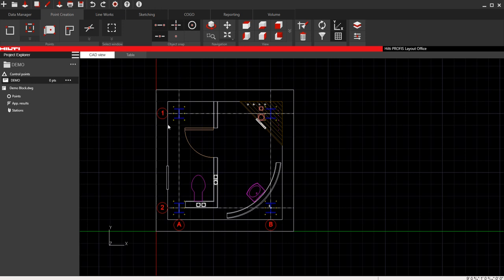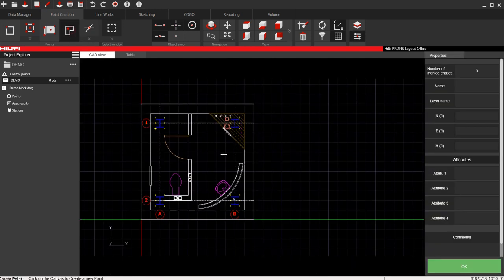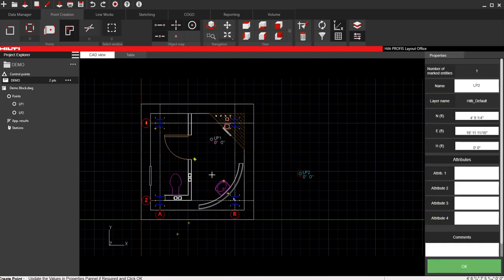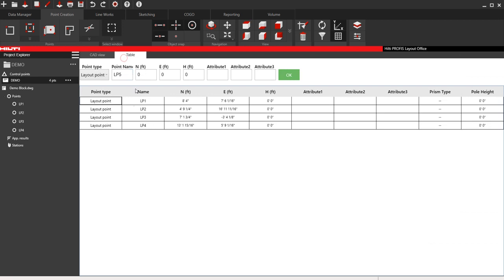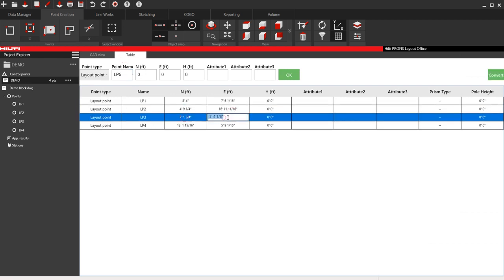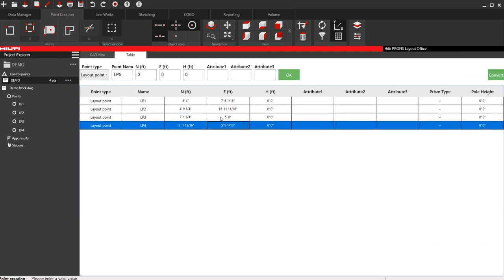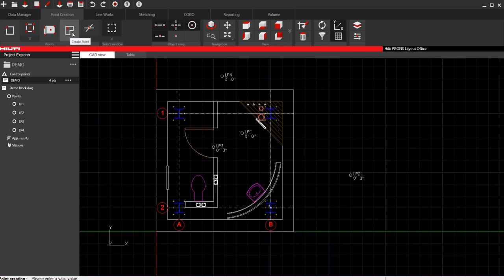So to finish up the point creation here, we're going to go to create point anywhere for a second, and this is literally just putting points out in the field, and you can come over here and edit their coordinates on your own. So if you need to create a point, you know exactly where the coordinate is, go here, create a point, change the coordinate, or go to table view, and you can change them in here as well. Right, so anyway, that's what that one does.